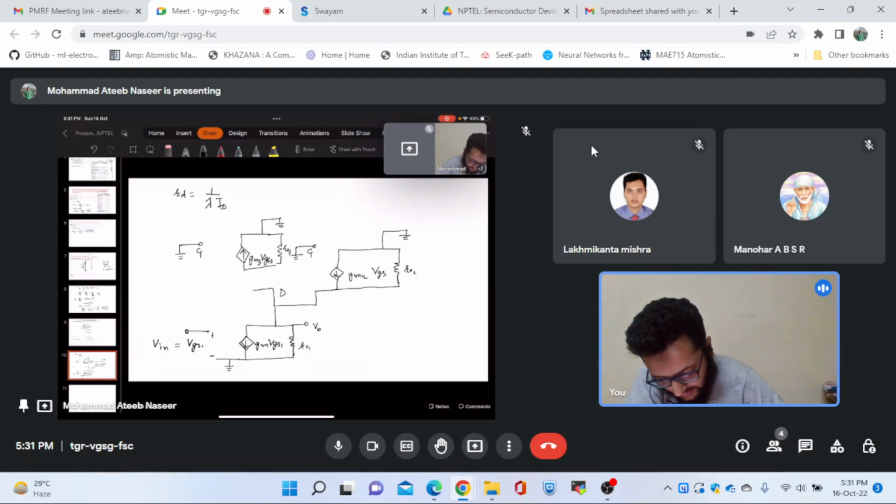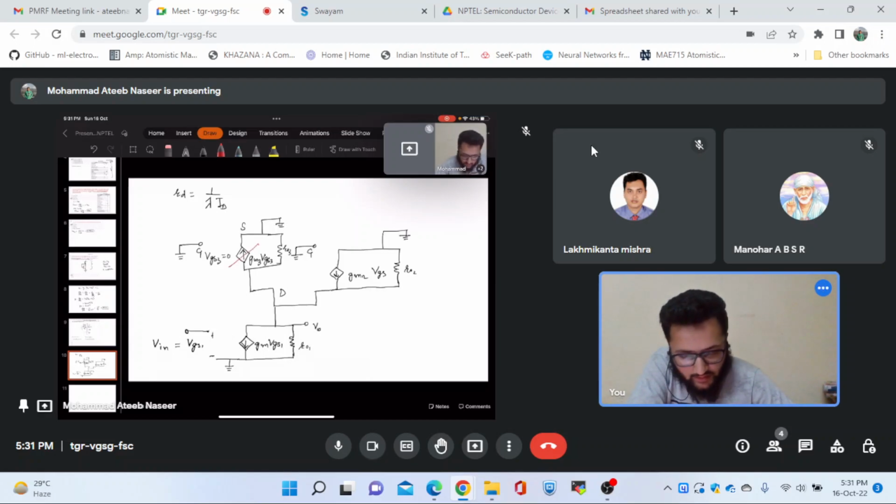And these are connected to this drain. Now we know this is the vgs3, and vgs3 is VG 0, S is also 0, so this is 0. This means this will go. There will be no current source over here to act upon.